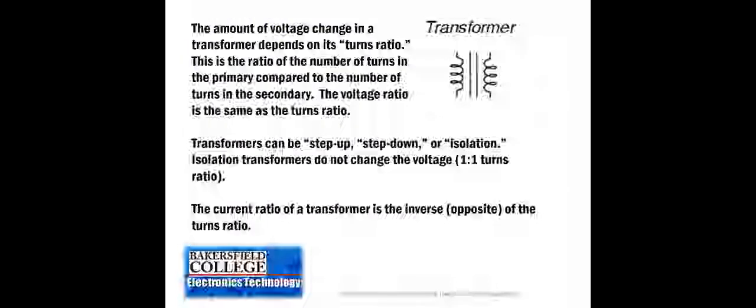We can change voltages by simply using a different number of turns. The number of turns that goes into the secondary, the motor itself, would be the turns ratio. At each point, voltage ratio and turns ratio are identical. So on 180 volts, we're not operating the motor, we can use a transformer to actually change voltages.